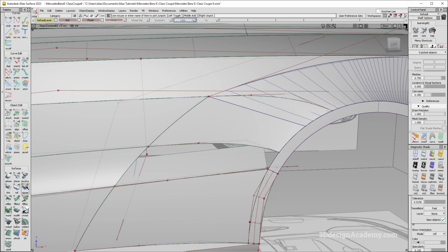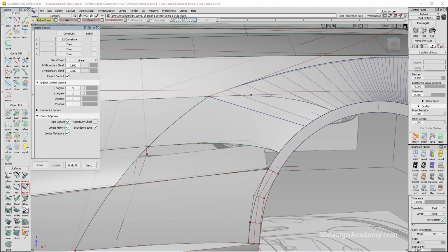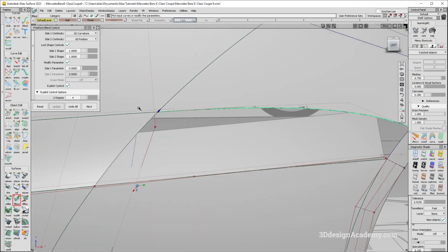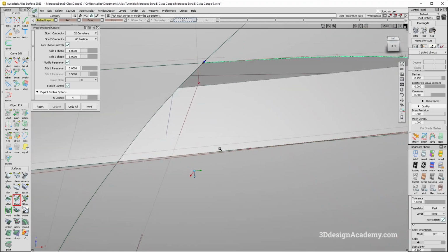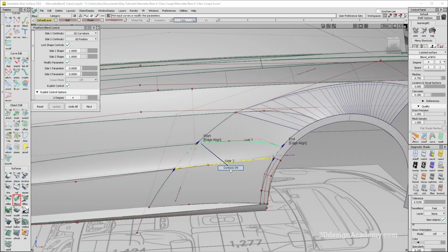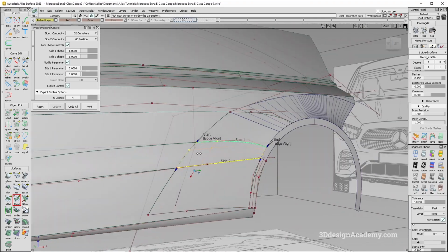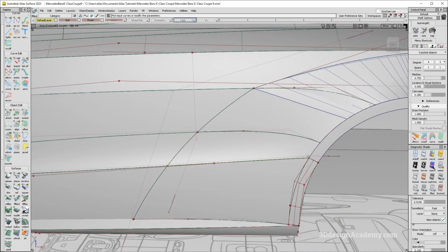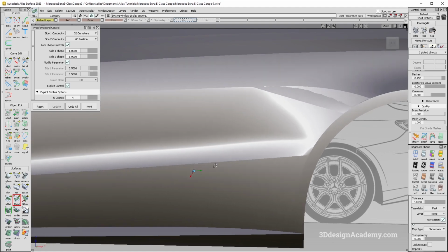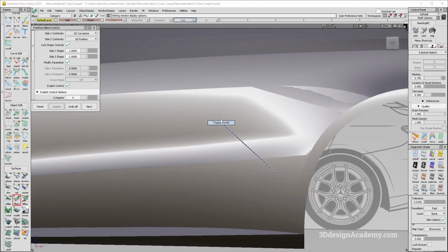And let's go ahead and finish it off with a, well, actually, because we got history to play with, and I don't think we're done playing with this one. So let's go ahead and line this over here like this. Edge align. It's going to just G2 on one side, position on the other. This should actually create a very satisfactory highlight over here. Okay, so I think that's good.